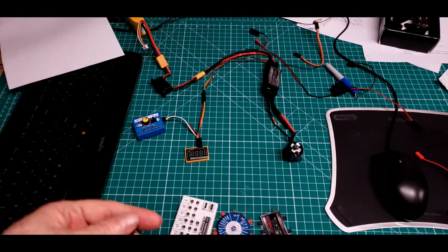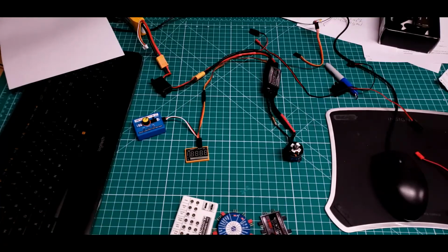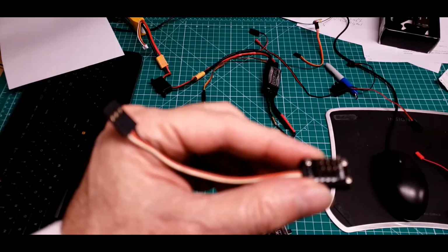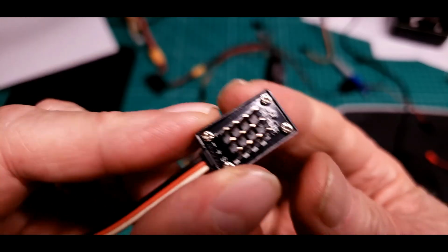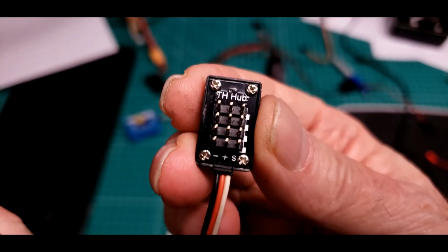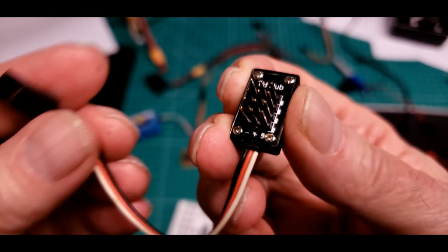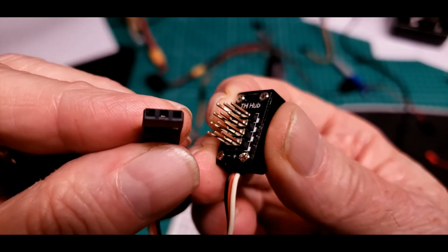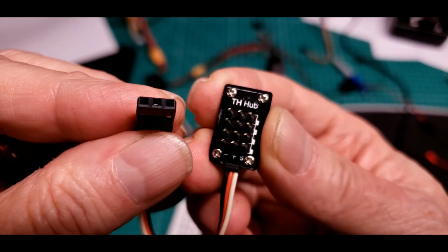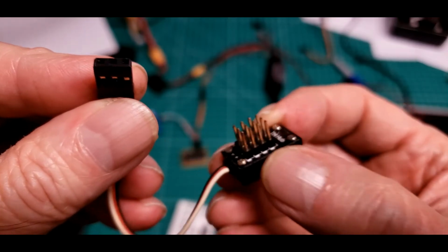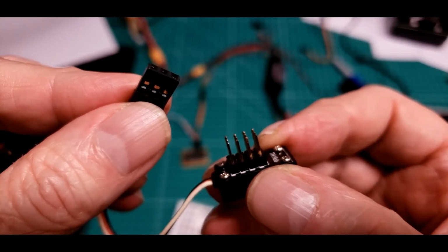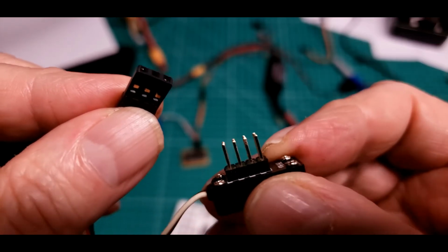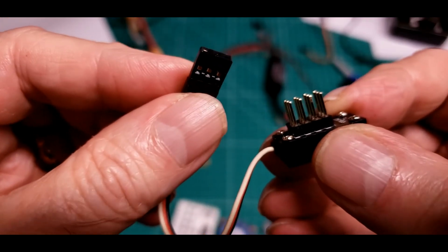Then when quads first came out and we had to program 4 or more ESCs at the same time, when we first started doing that, we used one of these little boards. This is called an all-in-one board, or a little hub. It just lets you plug 4 ESCs into it and has one input over here for giving it its calibration numbers. I've used 2 of these in parallel to program more than 6 at a time. You can still do them 1 at a time.